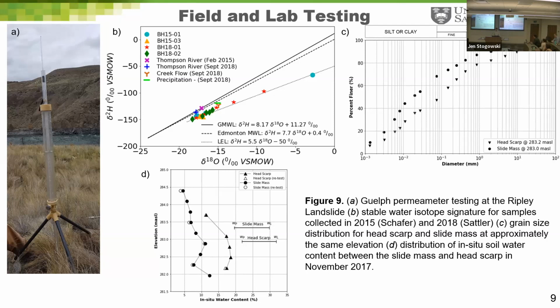In addition to these tests, several ASTM standardized tests were conducted for the recovered grab bag samples, including gravimetric water content, total suction with chilled mirror hygrometer, specific gravity, grain size distribution, liquid limit, plastic limit, and Tempe cell experiments. The data collected from this field program and laboratory testing filled in a material parameter gap that was missing for the upper till unit. Previous borehole investigations focused on the lower portion of the landslide due to the inaccessible nature of the upper slope.